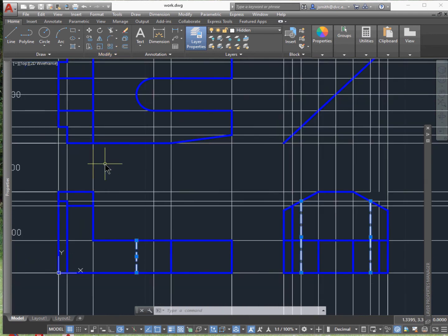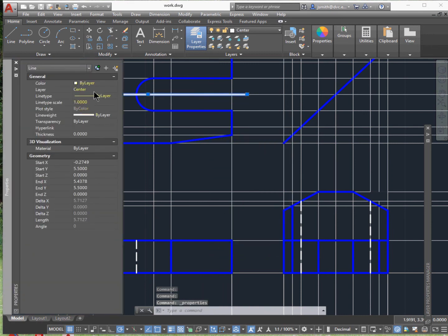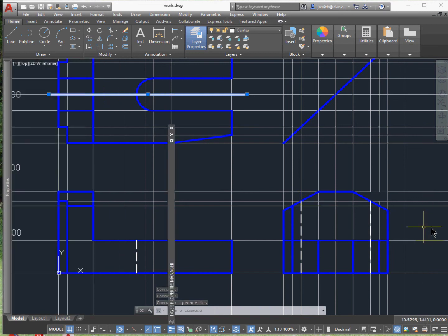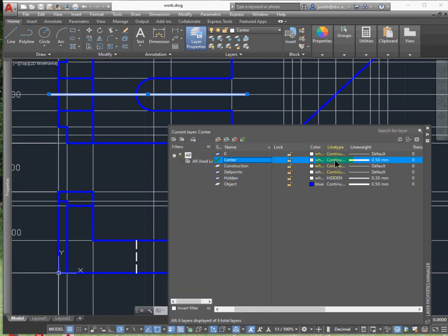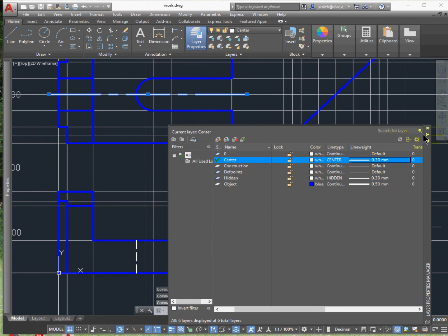I'll build those center lines, and then go ahead and take a layer, a line. I hover over. I'm actually not snapping on these points here. You'll see in a second. So hover over, go extend over. You want to extend these center lines beyond the part. It's very important. So if it's not on center line, so we're good. Make sure that this center line has the proper line type. All right. And actually, again, these actually are better left at 50 millimeters for the line weight.